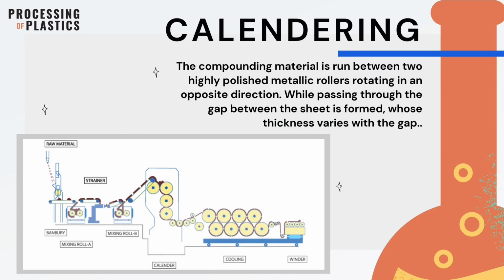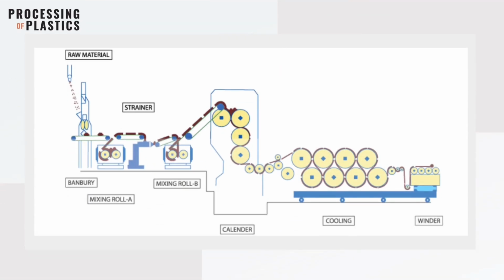Polymer granules are melted and compounded in the extrusion unit, as you can see in the figure. Then the softened polymer is squeezed, passing through heated rollers, and finally the plastic film is coiled at the winding station. Examples of these are plastics, papers, rubbers, and fabrics.